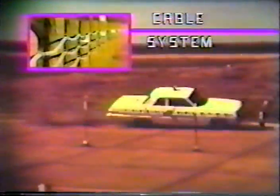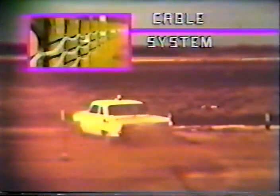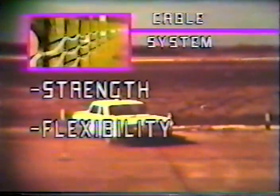In the cable system, the posts and cables need to be strong enough to hold the car in, yet flexible enough to redirect the car. Both the strength and the flexibility must be in the right balance. The anchors are designed to provide strength to the cable, hold the cable in place, and keep the tension tight. They're buried so that they do not become an additional hazard to the motorists. The height of the cable is also important.